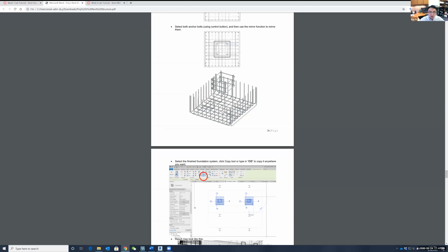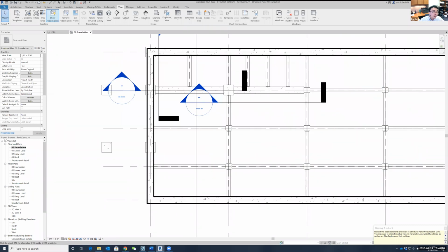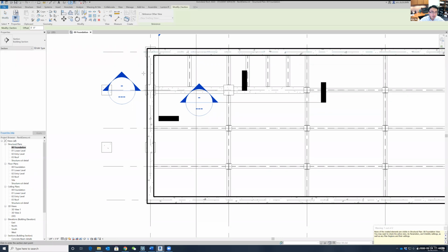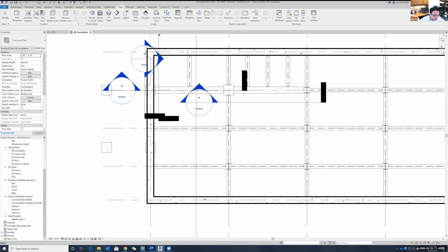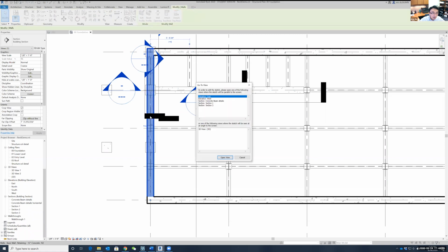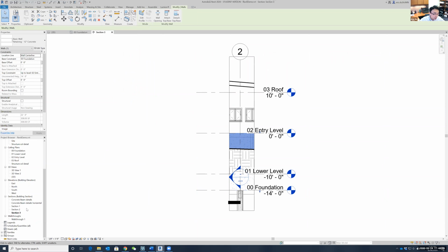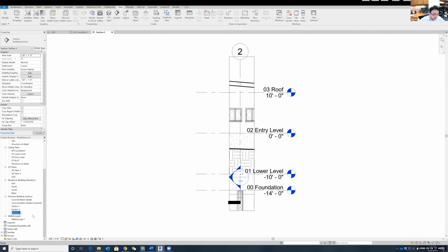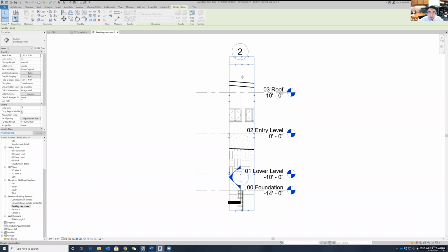Now, in order to build the rebars for the cap in two directions, we have to create a cross-sectional view in two directions. Make sense? So let's go back here and create a cross-sectional view for this guy. Let's go to the foundation and go to the view. If you still remember how to create a cross-section view, we probably need one here. Let's name that, which one is it? Okay, so this is section 3. Let me rename that as cap cross 1.